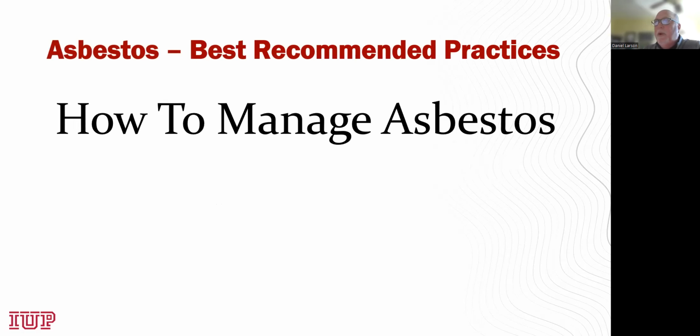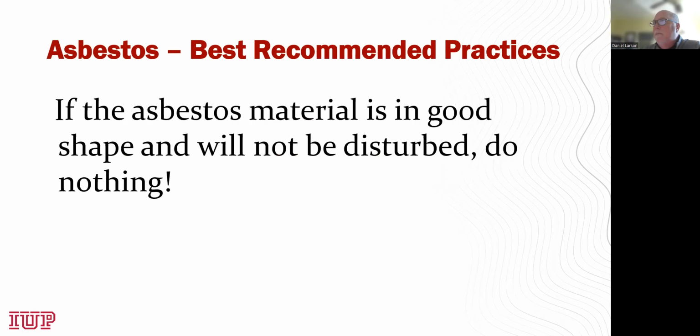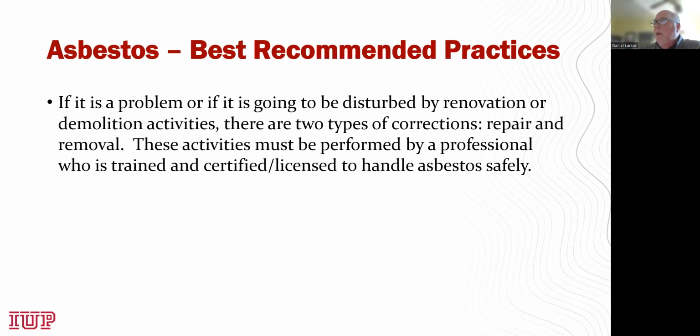So what are the best recommended practices to manage asbestos, whether you have employees exposed to it in a task or it's in your buildings? Really, if the asbestos material is in good shape and it's not going to be disturbed, you really don't need to do anything. Do not disturb it. If there is a problem with it, if it's damaged, or if it's going to be disturbed by renovation or demolition activities, then you really have two choices. You can repair it or you can remove it.